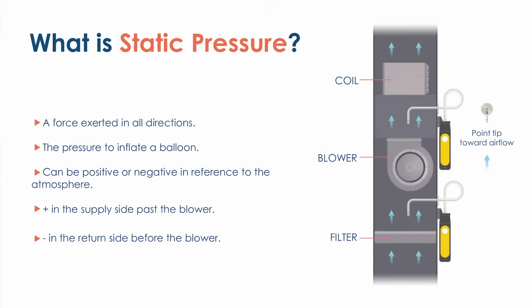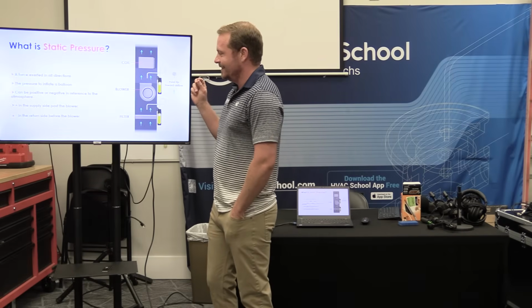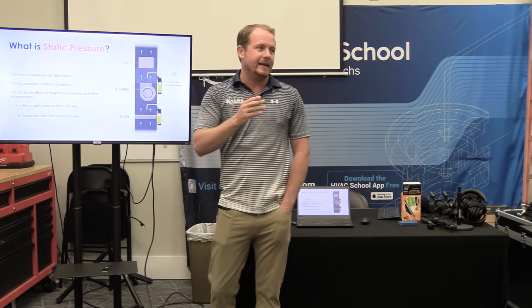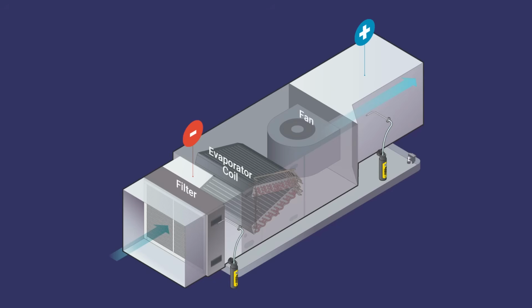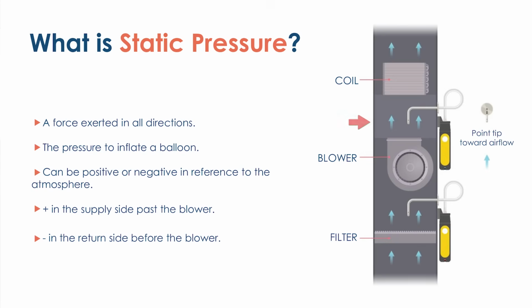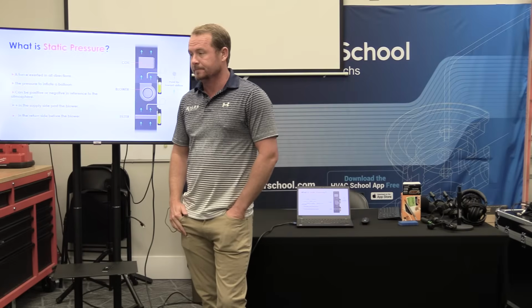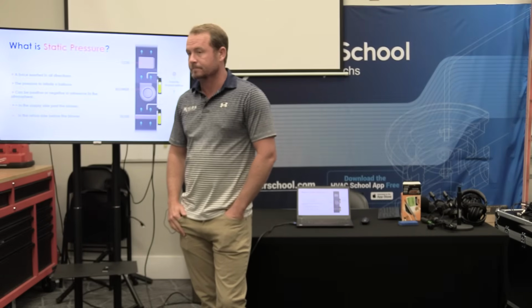In this particular case, we have positive pressure going through the evaporator coil. So where would we take the measurement if we're measuring total external static pressure? Does anybody know? On a gas furnace, right where we show it here. And does anybody know why? Because when we take a total external static pressure measurement on a fan coil or an air handler, a heat pump system or a straight cool system that's not a gas furnace, we would measure above and below the air handler. Why do we measure below the coil when we're doing a gas furnace? Why is below the coil the right place to measure?